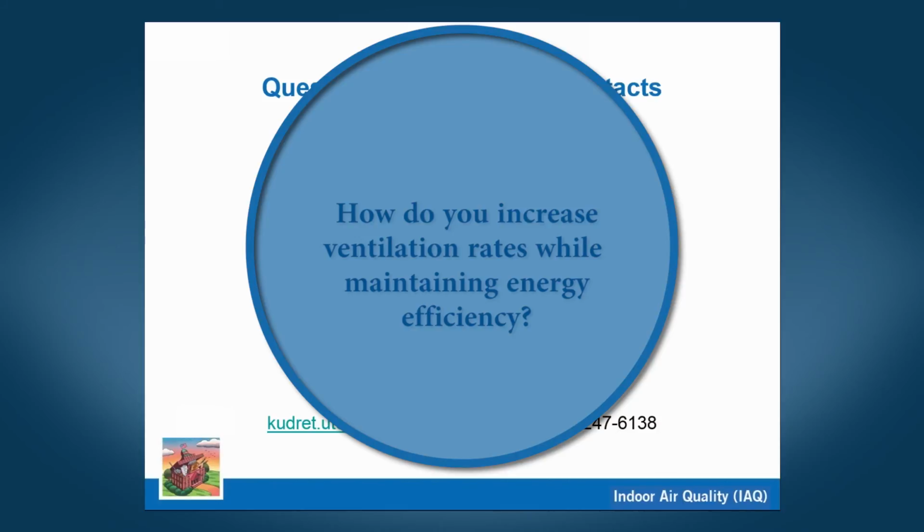Kudrat, an additional comment, sort of in Dave's case study. In teaching the BOC courses, I had a woman tell me that she paid for her salary the first year simply by finding the school that they were running 24/7 because they had air quality complaints, wide open, 100% outside air, and just returning it to some normal semblance of operation. If you run 100% outside air all the time, it's either too dry or too wet, and you're spending a fortune doing that.